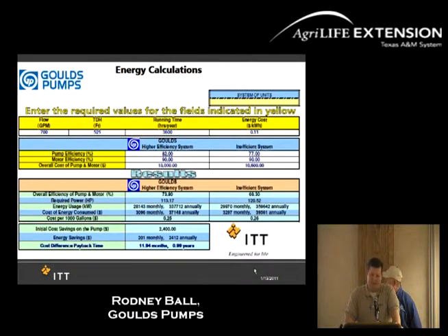And then we multiply it out times hours, because if you're watering corn, it's typically 24/7, 7 days a week within that time period. So what we did, we just left it run the whole time. And as far as the energy cost, we put it at 11 cents. This is actually close to a line shaft application, so therefore it's a little bit higher efficiency as far as your pump. So you'd have an 82% efficient pump, and your motor, which is a vertical hollow shaft motor, typically has a higher efficiency percentage, 90% versus one that is 77%.